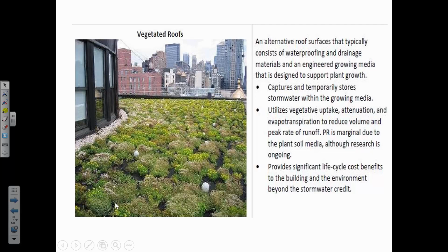These are a lot of expense and a lot of maintenance, though, relative to the benefit that they provide. There's generally lower hanging fruit available for reducing peak runoff than creating a green roof. The green roof only makes sense if there's going to be some added benefits of people going out there and enjoying it and the beautification aspects. But from just the strict standpoint of the volume of water that's detained and the expense of reinforcing a roof to carry that added load, it doesn't really make a lot of engineering sense unless you have some of those qualitative benefits added in as well.